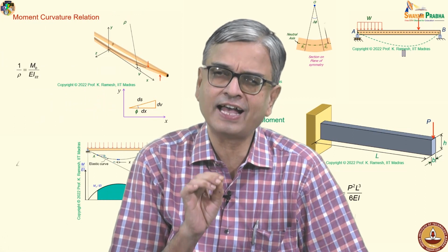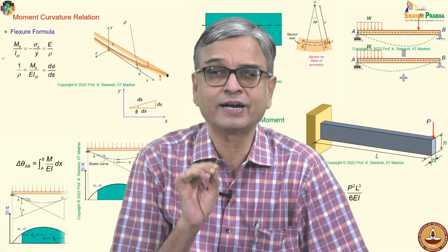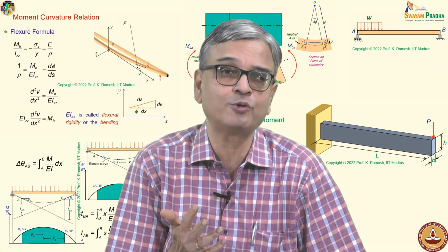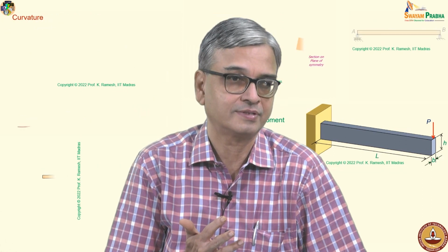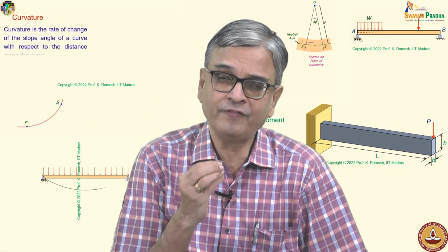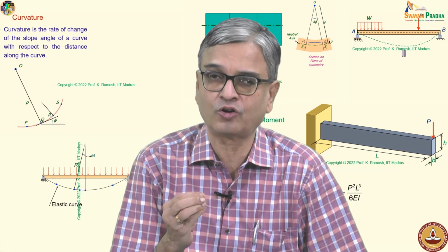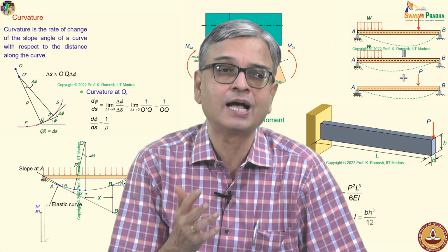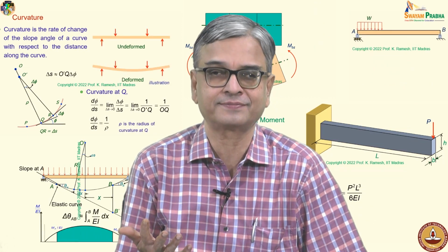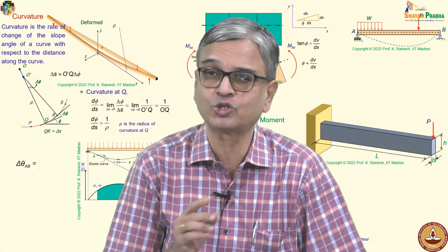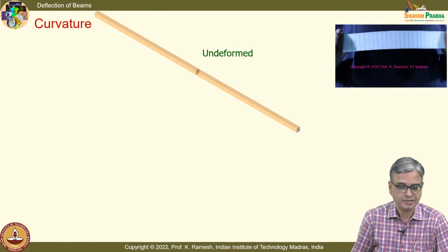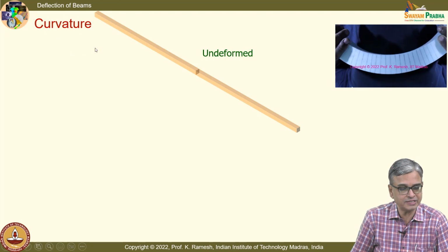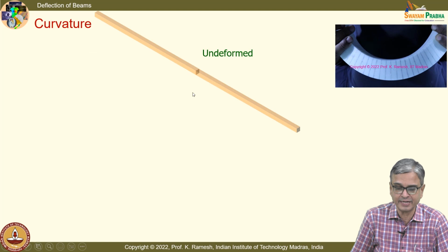And deflection is fairly simple provided you understand and recall what you have learnt as idealization of supports in your earlier course. And I have always emphasized experimental knowledge, and you should be able to visualize for the given supports how a beam can bend. That would be the focus of the lecture also today. And it is closely related to curvature. That is how we relate the deflection to the bending moment.